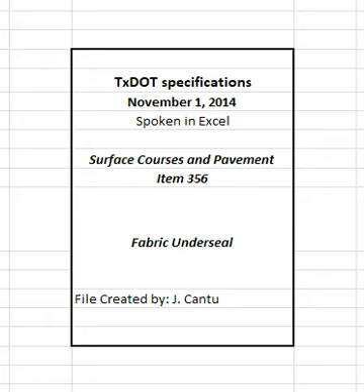Do not allow joints or laps in the underseal material for transverse pavement joints. Minimize underseal material joints in longitudinal pavement joints, and do not allow overlap. Center the fabric width over the joint. Apply fabric to the joint with a minimum of 5 inches on each side or as specified on the plans. Do not allow air bubbles under the fabric.